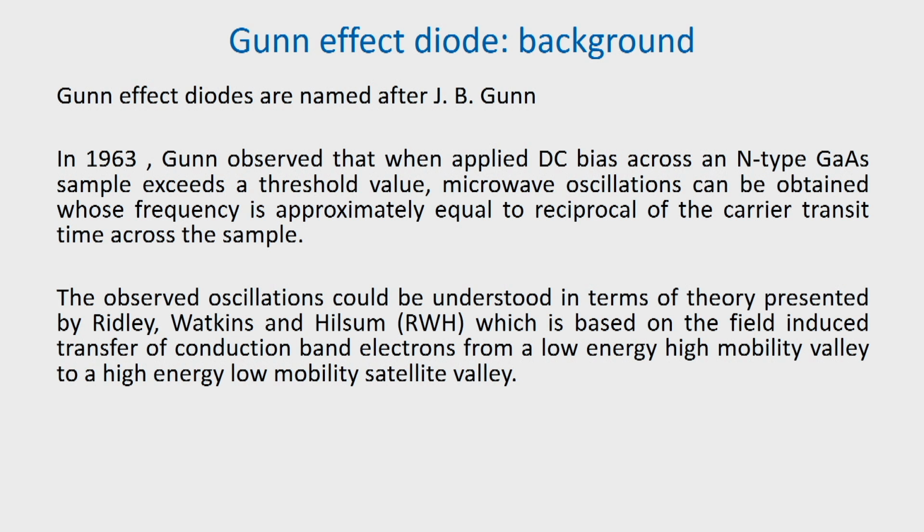Now, the observed oscillations could be understood in terms of the theory presented by Ridley, Watkins and Hilsum, popularly known as RWH theory, which is based on the field induced transfer of conduction band electrons from a low energy high mobility valley to a high energy low mobility satellite valley.